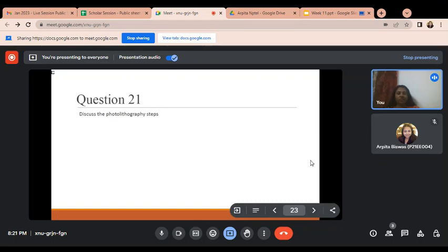And then we go for the UV exposure, and after the UV exposure we go for the development process. During the UV exposure, photolithography is the pattern transferring process. So the pattern is transferred from the mask to the underlying layer or the photoresist.